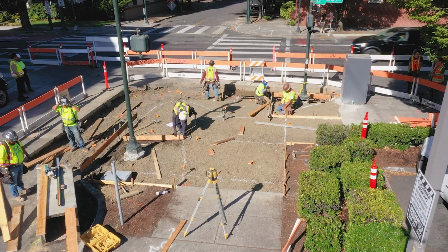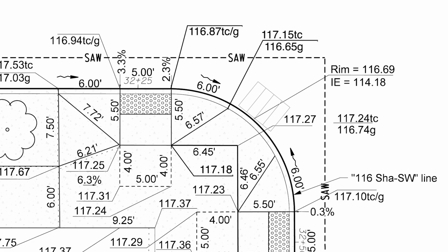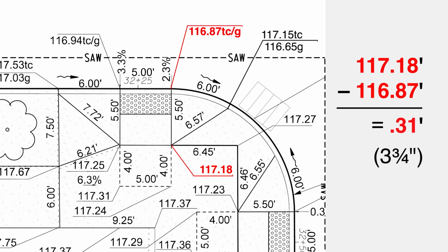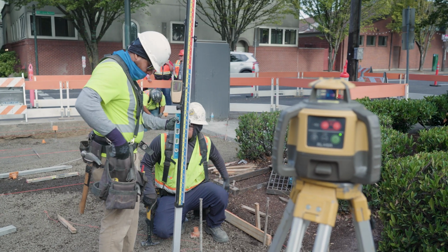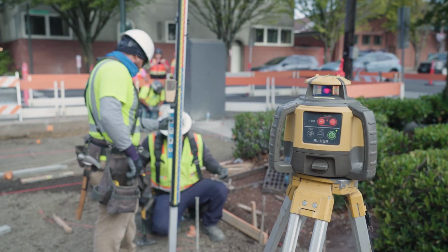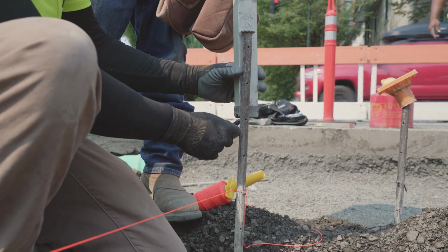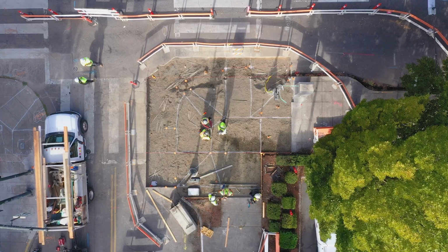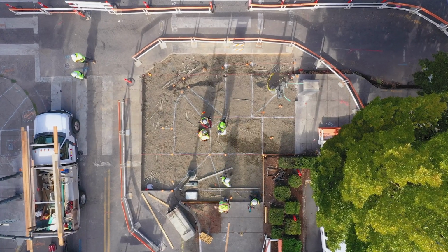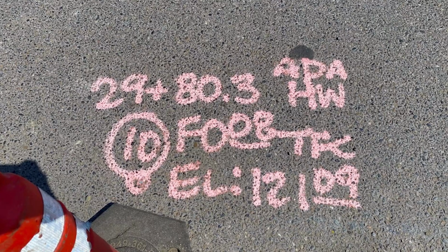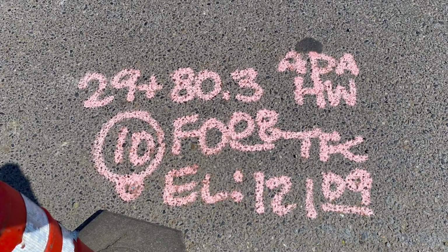Here's how it works. You remember the elevation numbers on the plans we showed you a minute ago? And you remember how you can easily subtract a smaller number from a bigger number to get the height difference between them. Well, a construction laser level gives you a number, the same number, anywhere on your site, to measure off of to nail the elevations on the plan. That's because it starts from a rock-solid reference: one point on or near your site that surveyors have certified to the 100th of a foot.